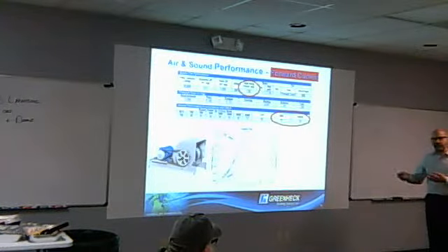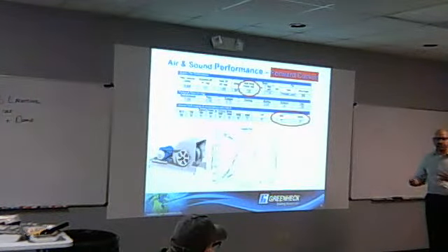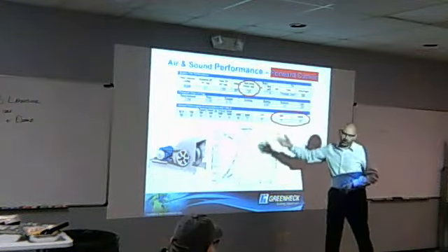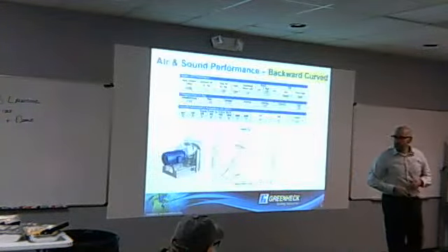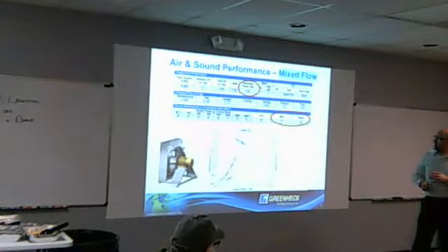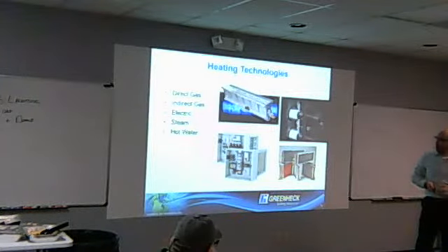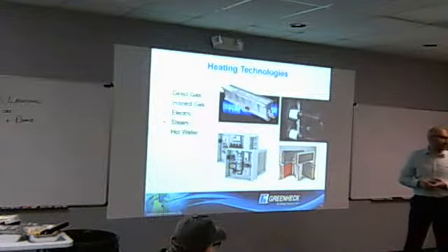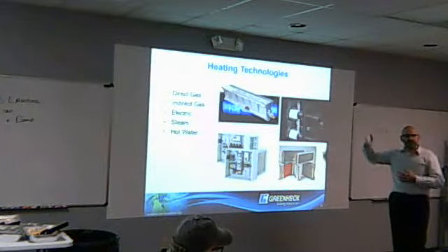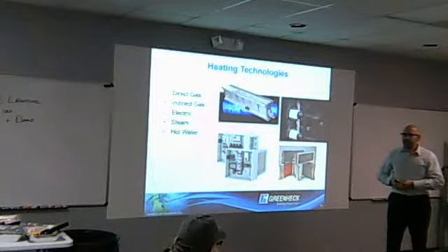One more time, 79 to 82, a difference of 3. You may or may not notice, some people can notice the octave bands differently or the tone, it just depends. But know that mixed flow has definitely sound advantages too. In terms of being finished with fans, any questions on those? I'll rifle through those because we want to get into the makeup area, but okay.